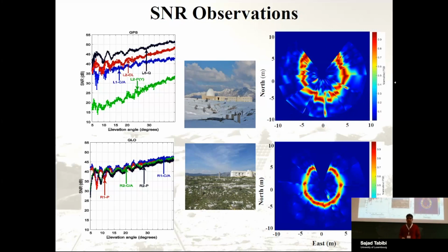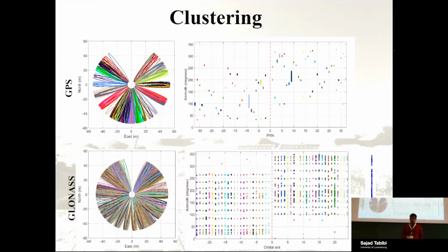So as you can see, we have different kinds of precision around the GPS when we receive this kind of signals. In addition, the observations also have different noise levels. So when we want to extract these parameters and combine them, we should come up with a model to help us improve these solutions. Again, as you can see, different azimuth angles. The center is the location of the antenna, and when we move in different directions, the properties of the signal change depending on the azimuth angle and the elevation angle of the satellite. So we need to come up with a solution to improve this.